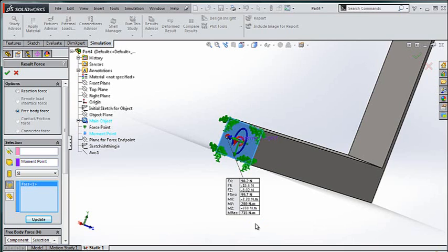But then if you look at the resultant, you see that the resultant is actually 715, and that is what we calculated by hand. So I absolutely don't know how you could get a happier answer than what we have here, but this is really, really great. We're able to put this together, create it in SolidWorks, put in all the extra forces, and get the exact same answer out that we expected, so all is well with the world.